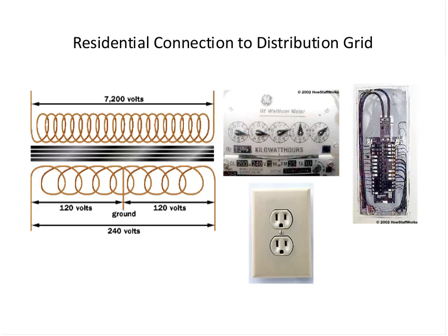So you have some appliances where you put it on the two ends, and then you get the 240 volts, or if you tap it in the middle of the transformer, you get the 120. So every house, at least as I understand it in North America, has this possibility. So if you have a washing machine or any kind of high-power device, that may require 240 volts. And then the typical voltage in the house that's coming to the wall is 110. But this is how they break it up.